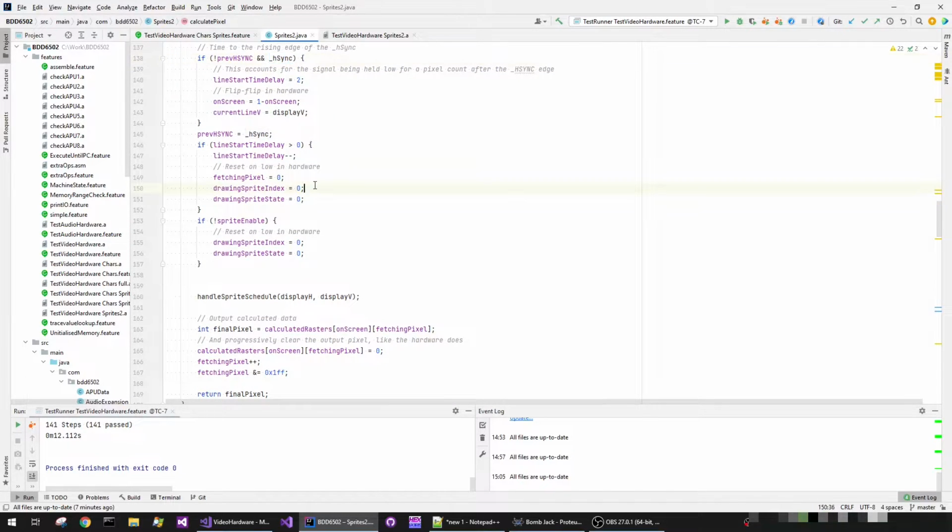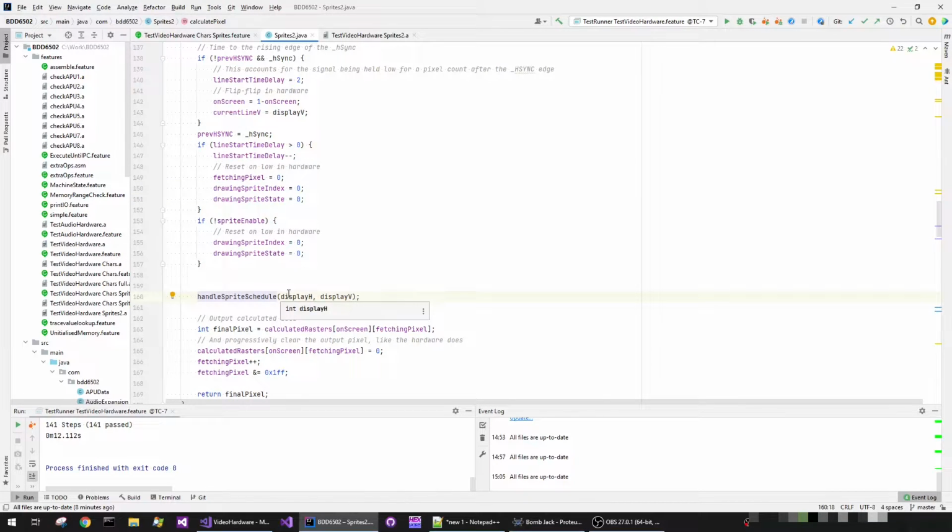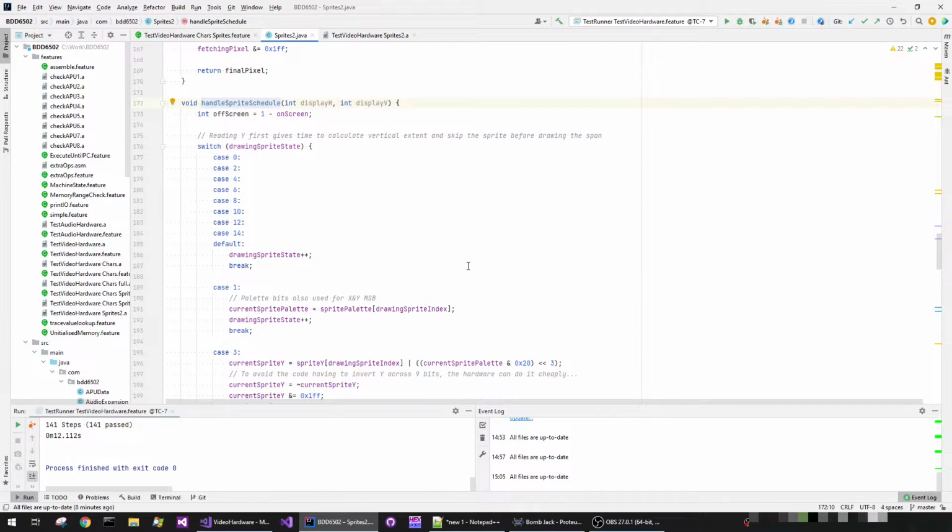Some of the other layers start displaying or calculating the new scanline 8 pixels after the end of the visible data from the previous scan, which means that the characters, the tiles, and the old sprites method would need a little re-engineering to start triggering their calculation on the positive edge of H-sync instead.